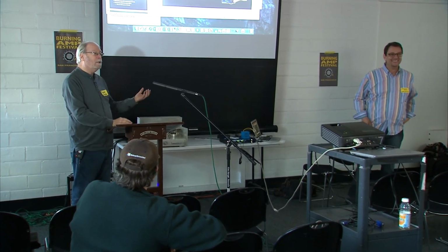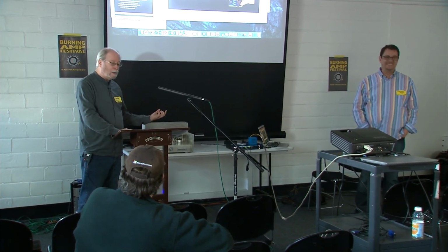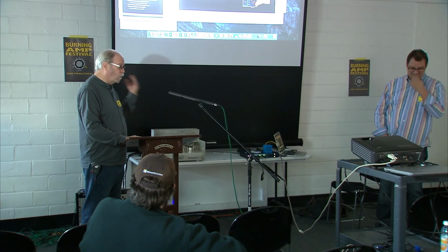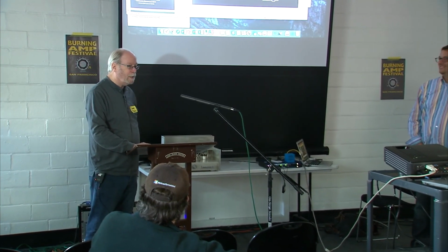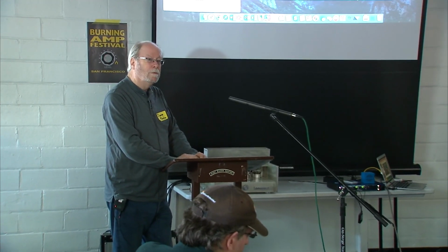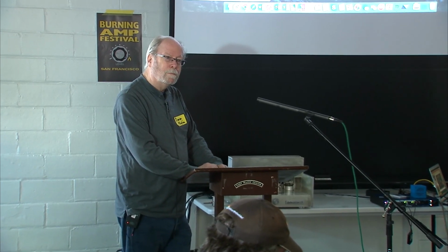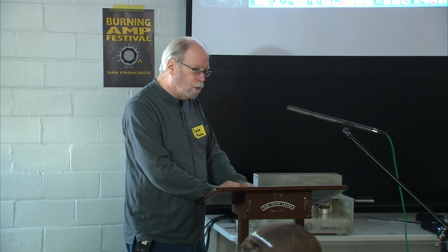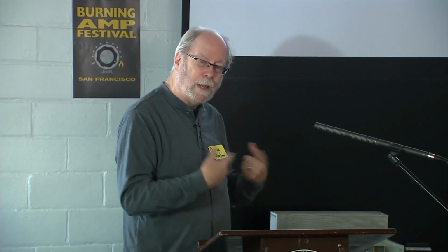Yeah, they're designed to literally tell, are we about to burn up the voice coil, and they moderate it back, because the voice coils are fragile and you don't want it to break, but you got to push it pretty close to get any sound out of them. I know, so they actually monitor the temperature of the voice coil, and they're making this called speaker protection. Yeah, TI calls it their smart amp, and they have this whole process for characterizing the voice coil, figuring out the temperature rise, and predicting it. It's pretty sophisticated, and it's something you can only execute with some sophisticated DSP, but it really does work. But right now, they only have one chip that you can even use at 20 watts. Everything is way low power.